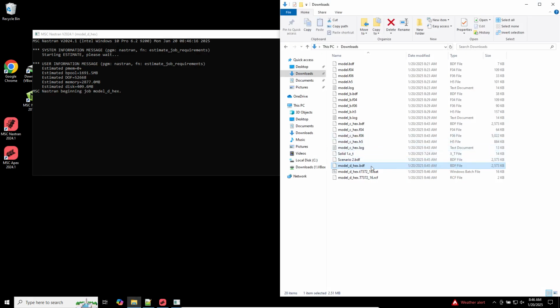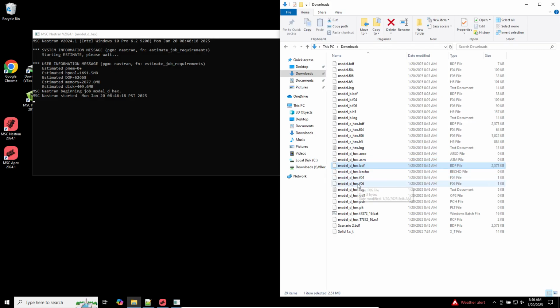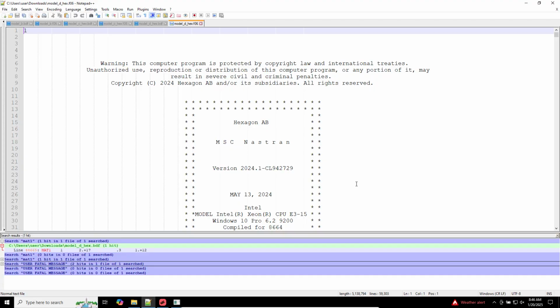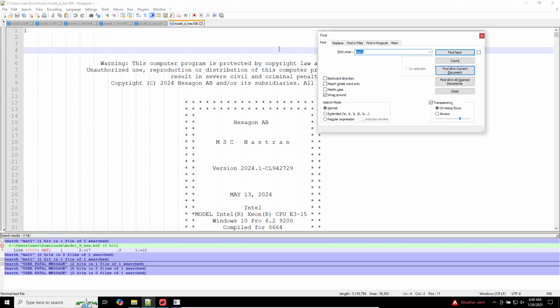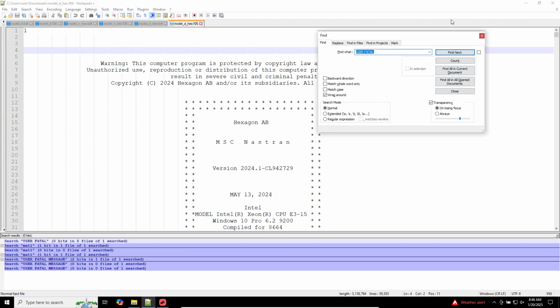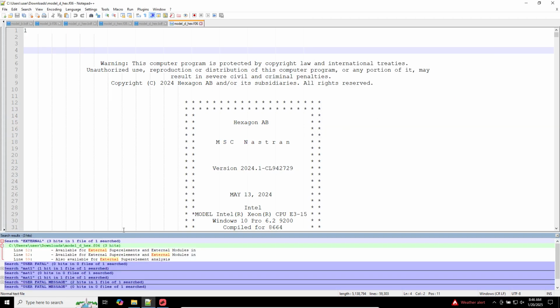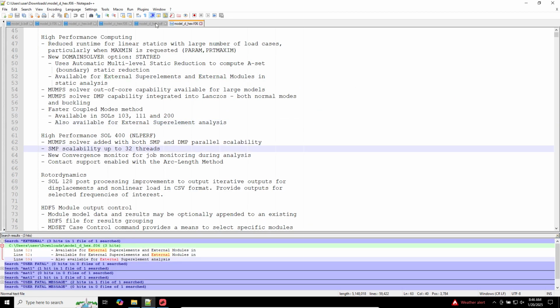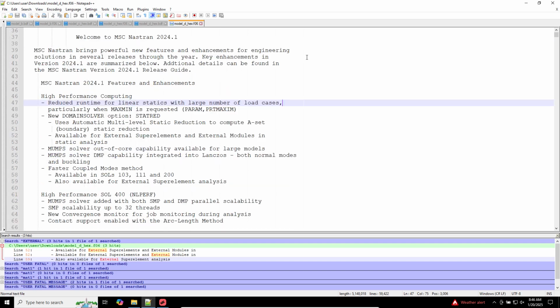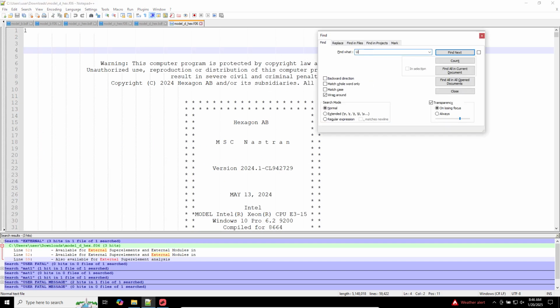Let's open the F06 file that we get in a moment. And let's look for any errors in this example. So user fatal. There are no errors. Now, do we get external work? Let me go ahead and see if I can find this. Was I looking in the right file?